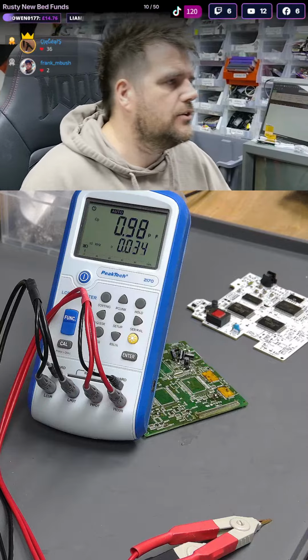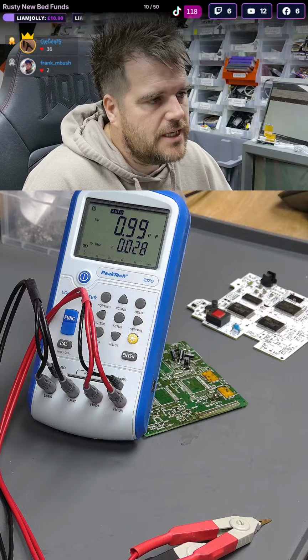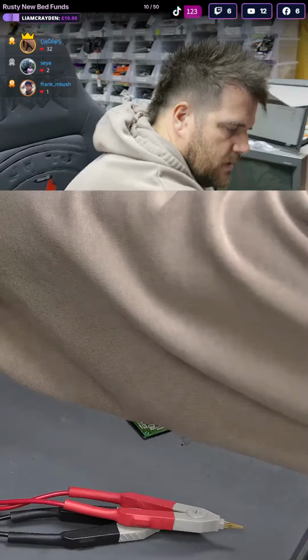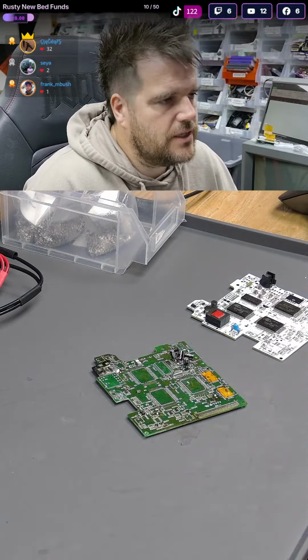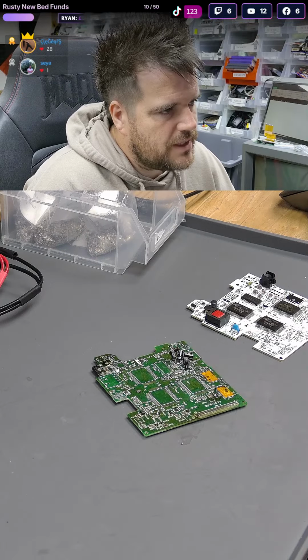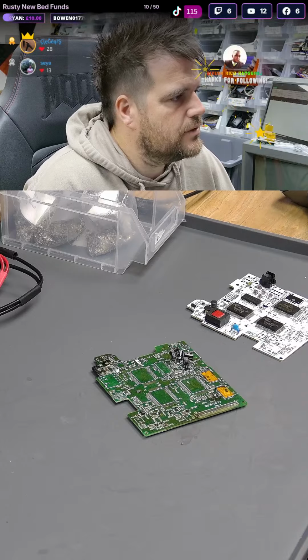Slightly non-standard. Let's see if maybe the PC Engine's schematic, the desktop version of this, has any caps in a similar range and in a similar area, just to give us a bit more feedback so we can make the right choice. If not, the reading will be accurate enough, it won't be a problem.